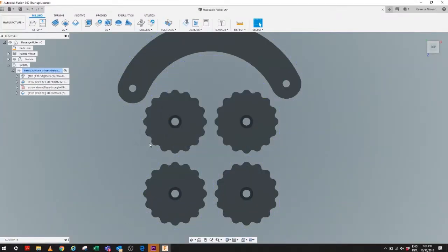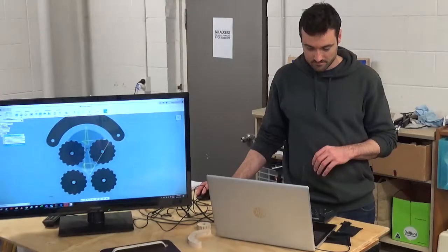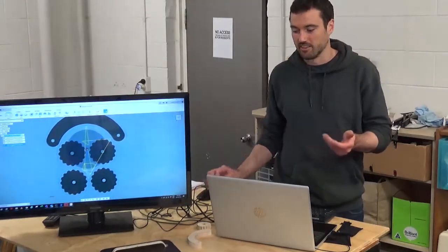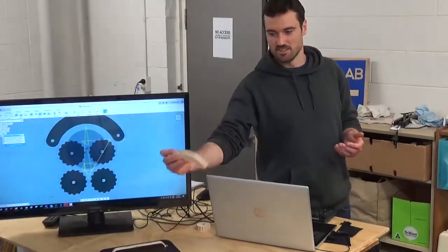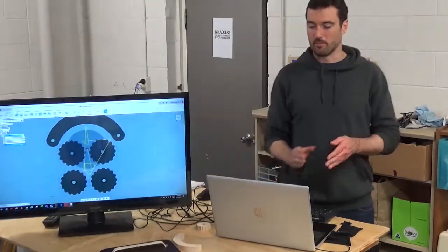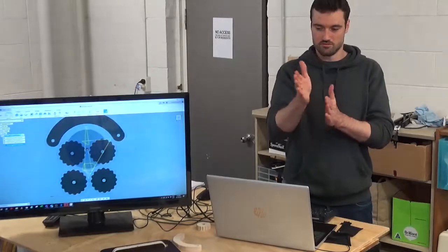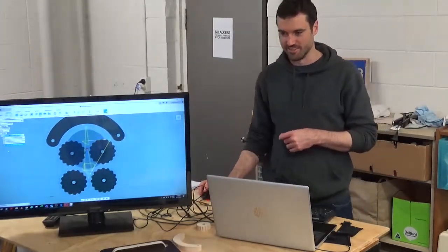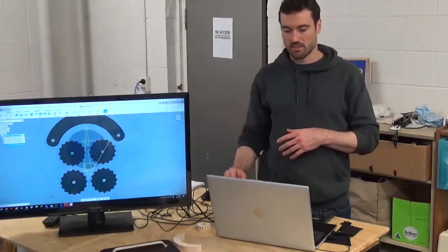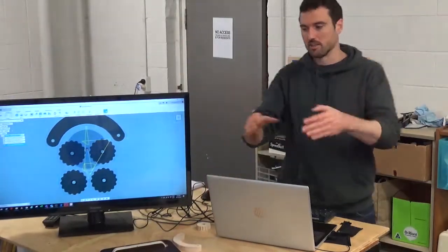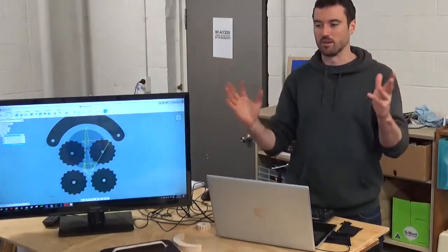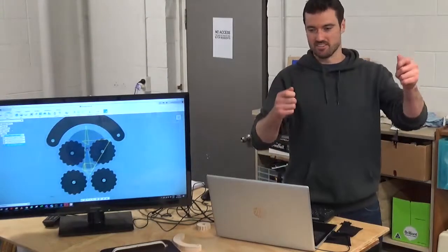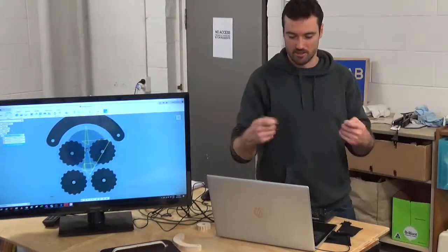It's interesting how the tool goes outside of the stock. It does, and that's fine. In this case, I just misjudged it slightly. But basically, if that blue line goes right down the stock, you've judged it really well. The piece of stock that we use is likely to be quite a lot bigger than this because it's not that scientific. We get a big piece and go, yeah, that'll work. Put it down and make sure it fits.